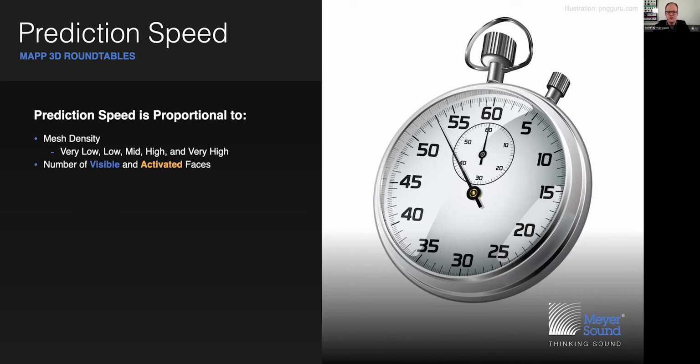The other thing that you need to know is that the prediction speed is also proportional to the number of, mind you, both visible as well as activated faces. That is to say, activated for prediction. You can have a gazillion faces visible within your model, but if only one of them is activated for prediction, then you're still going to have a very speedy calculation.